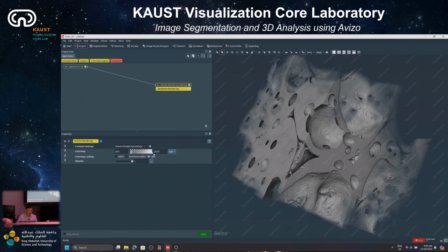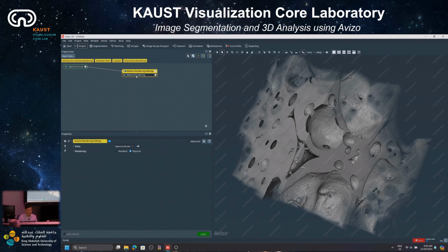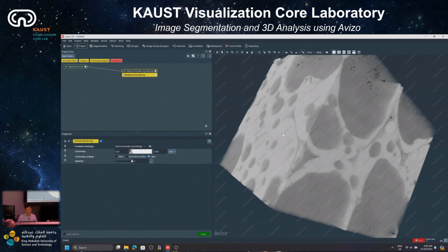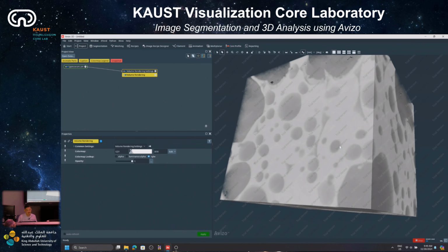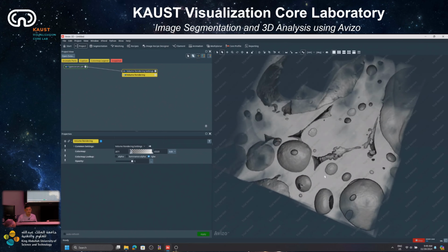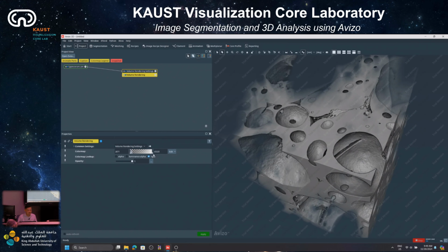So you can set the dynamic range of the color map. So in the volume rendering module on the bottom tab, just adjust the dynamic range of the color map, or you can just easily click on edit, adjust range to data histogram. Get this kind of, but the data histogram is not very good. Just do data window. But you can adjust further to make it more solid or more transparent.